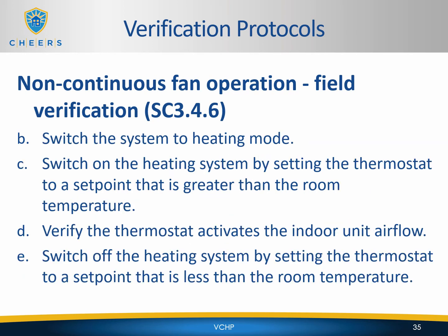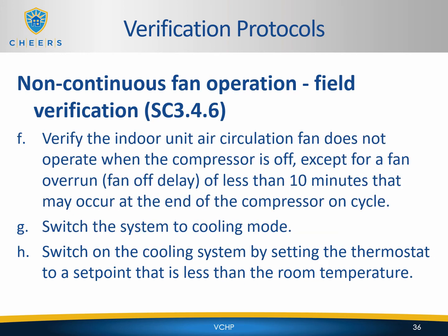Switch the system to heating mode, and then switch on the heating system by setting the thermostat to a set point that is greater than the room temperature. Verify the thermostat activates the indoor unit airflow, and then switch off the heating system by setting the thermostat to a set point that is less than the room temperature. Verify the indoor unit air circulation fan does not operate when the compressor is off, except for a fan overrun or fan off delay of less than 10 minutes that may occur at the end of the compressor on cycle.